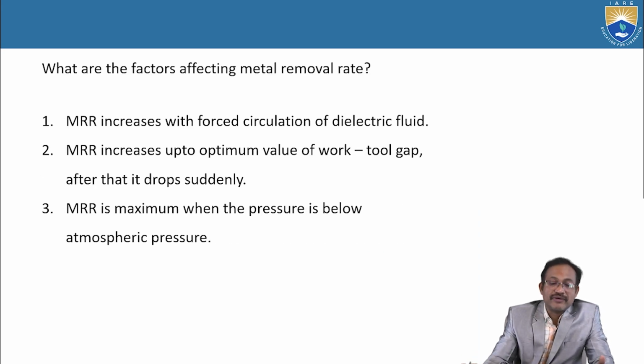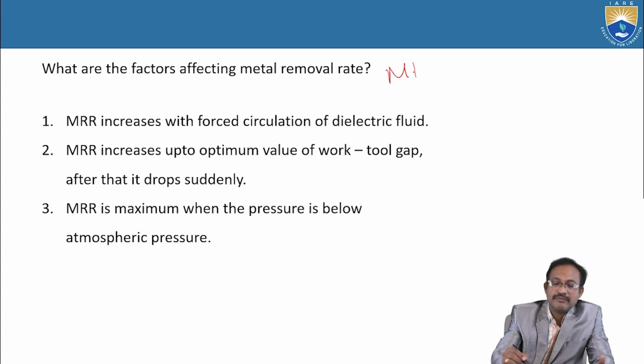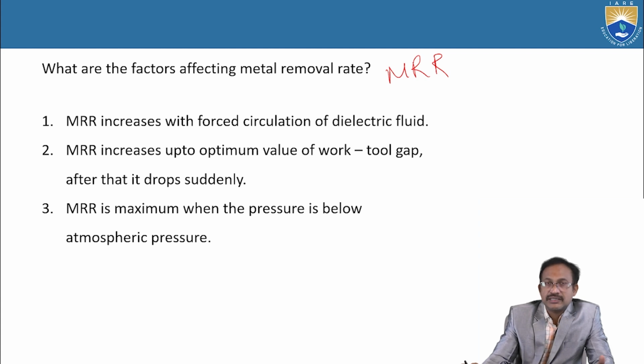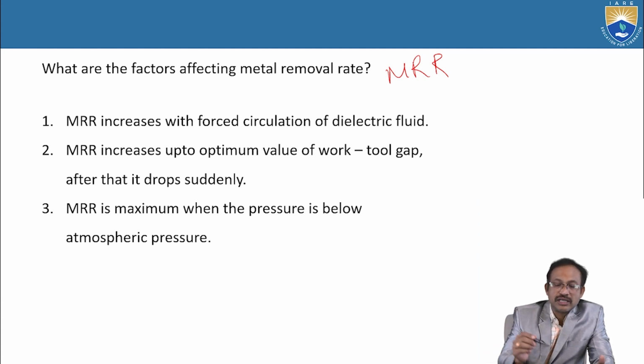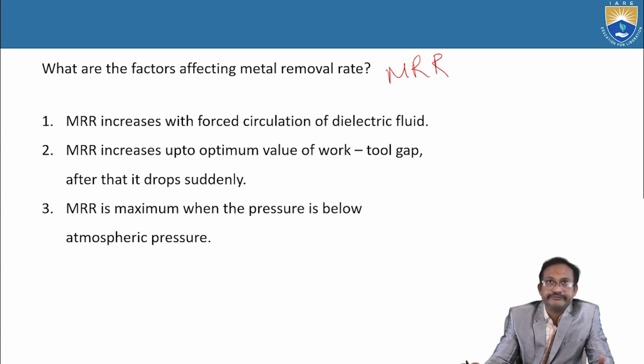What are the factors affecting material removal rate, MRR? MRR increases with forced circulation of dielectric fluid. MRR increases up to optimum value of work tool gap. After that, it drops suddenly.